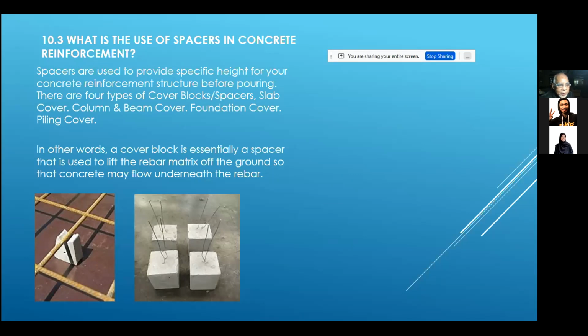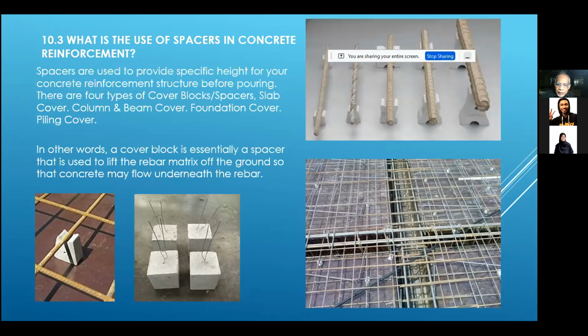I've seen some projects where the spacers are quite far apart, and the reinforcement starts to bend. When it bends, it will touch the floor, I mean the formwork below. When you cast and open the formwork, you can see part of the bar being exposed. That is why, before they pour the concrete, the engineers have to check to make sure that all these concrete blocks have been placed in the right place, and none of the reinforcement is sagging, so that it won't be touching the formwork at the bottom. If it touches, it means after you cast, you can see the bar being exposed.